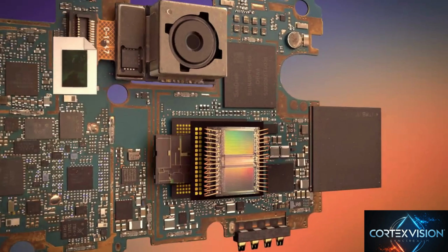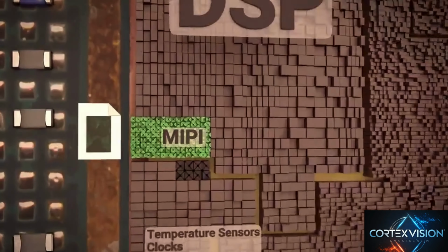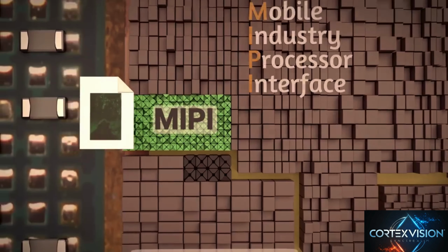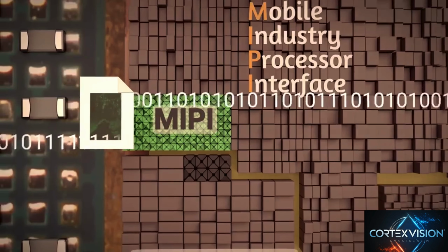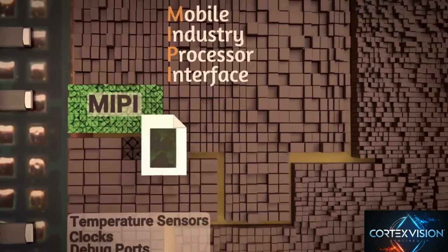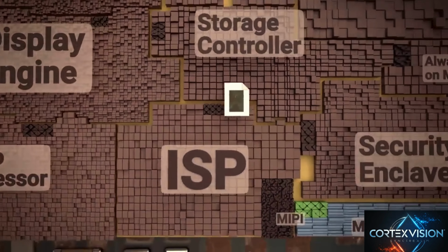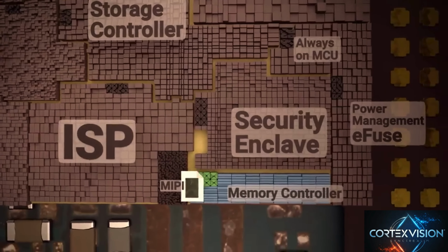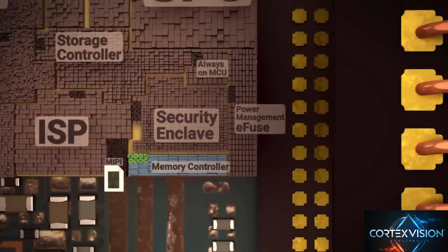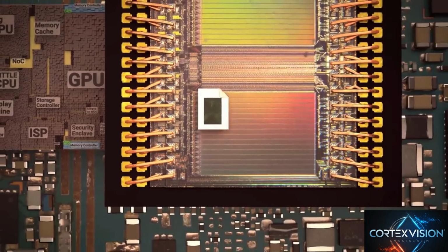To do this, the data travels from the camera and enters the SoC through a Mobile Industry Processor Interface, or MIPI, which can send or receive data at around 5 to 8 gigabits per second. This image data is then routed by the network-on-chip arbitrator through the SoC to the memory controller and into the DRAM, which, as mentioned before, is located on the die above the SoC.